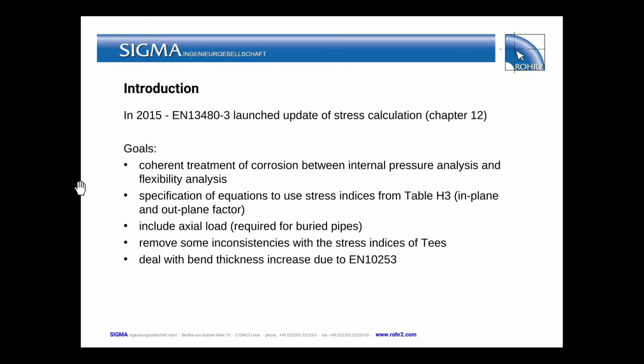In 2015, the working group working on the EN 13480-3 launched an update of the stress analysis calculation chapter 12. The goal was a coherent treatment of the corrosion between the internal pressure analysis and the flexibility analysis. In the specification of the equations, the stress indices from H3, in-plane and out-of-plane factors, were taken into account. The actual loadings were also included in the stress equations.